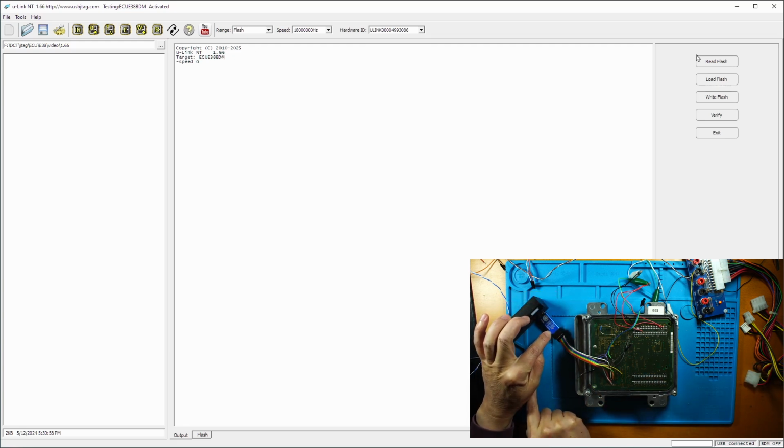This is the indication of the activity. You see here when you do the read, sometimes you see fast flashing. If you see this stop blinking for a long time, then this may be something wrong. You need to power cycle the USB.